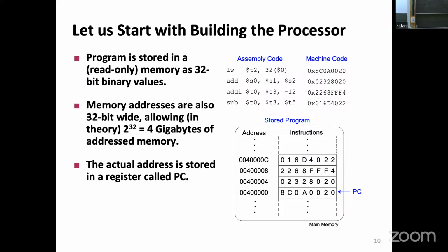Technically, you could argue that, hey, Frank, you could maybe self-modify the code, write it back. Let's not consider that for a moment, okay? Let's just assume this is a nice memory which contains the data that we want to read out. And the data is also 32 bits. And this is more or less it. It's a combinational logic block. We are not writing to it. So this is my instruction memory. And I promised that I would be drawing these in yellow, and I didn't. Let's do this.